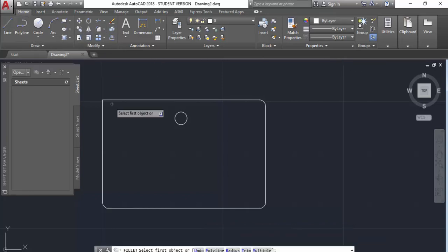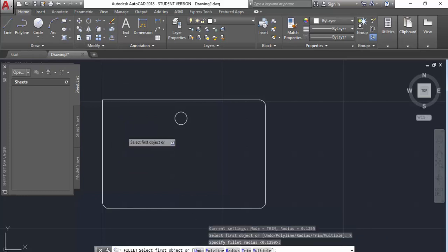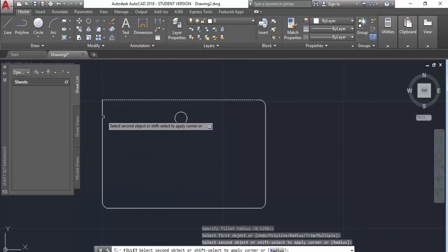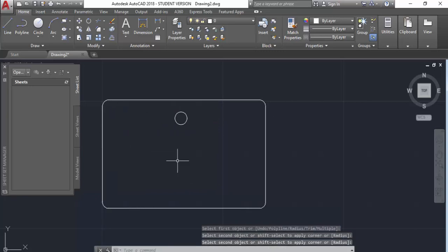Select that. Again, we'll go by radius. Hit enter again, because remember the last radius I selected. Click on that line, and click on that line right there. Okay, good. So there it is. We got our bag tag design. Well, I'm going to go ahead and hit stop for now, and I'll come back and we'll put my text in.